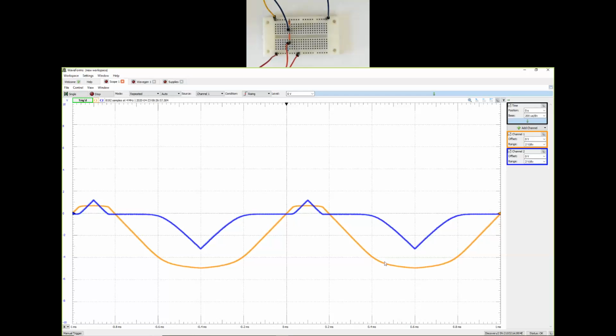The orange line, as you can see, is the voltage across the Zener diode. And on the positive side, it is getting limited to 0.7, very similar to the 1N4148 diode. But on the negative side, it goes down to about -5, but around that value, it sort of flattens out. So it's not giving us the good triangle wave as you would expect without diodes present, but it is getting almost like a clipping effect or a limiting effect around -5. So let's actually see what those values are by exploring the IV characteristic.